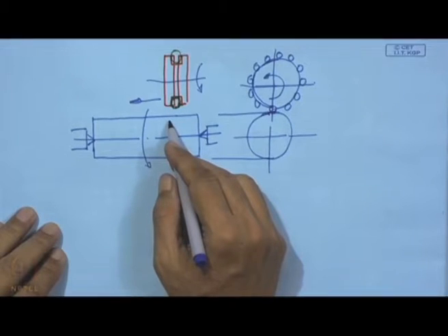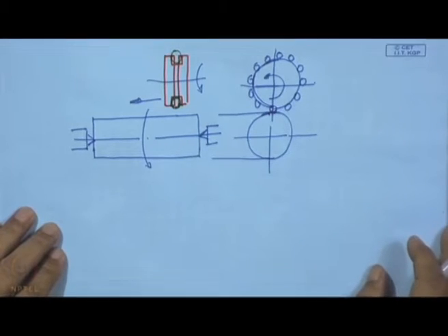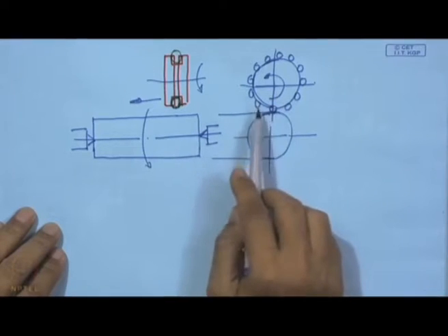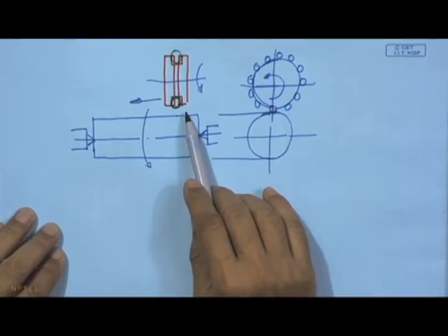Obviously for this reason, this shaft, which is a mechanical component in any application as a rotating element having alternating stress during a cycle of rotation, the material property which gets a little deteriorated by the grinding action can be recovered by this ball burnishing action through plastic deformation and by inducing compressive stress.